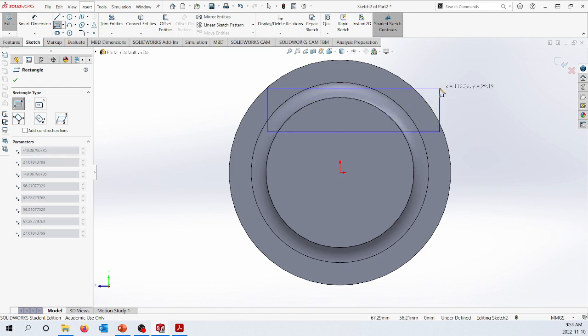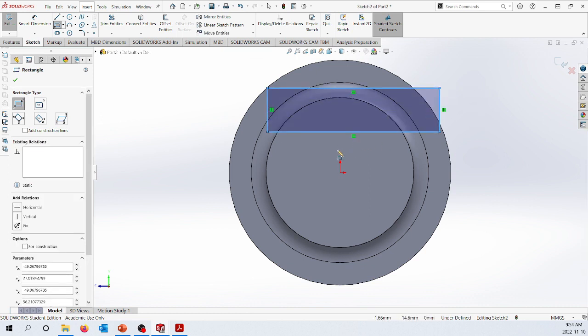I'm going to make an oversized cut. Last time we made cuts that lined up perfectly, right? We were exactly to the edges of our part, and they were snapped to the edges of our part. I'm going to make my cut purposely too big. I'm not going to worry about making exactly this little crescent-shaped slice of my circle. I'm just going to make a rectangular cut and then decide how big that rectangle should be.